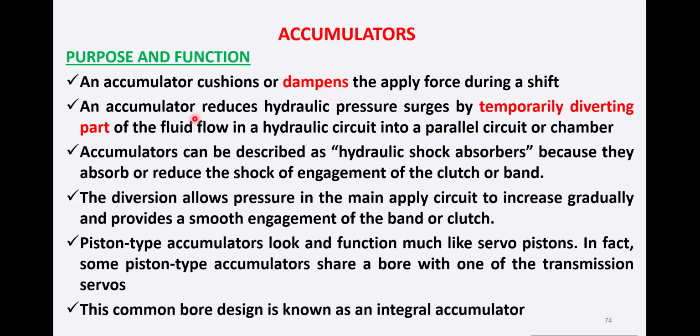An accumulator reduces hydraulic pressure surges by temporarily diverting part of the fluid flow in a hydraulic circuit into a parallel circuit or chamber. So basically it reduces the surge or the peak vibration which we experience in the conventional transmission.